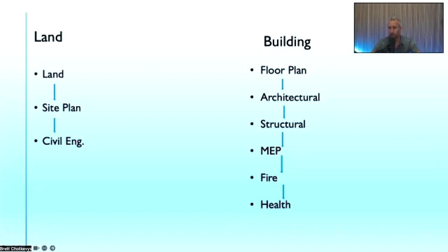So you lay out the 2D, then he's going to go through and build out, okay, now here's the walls, here's the roof pitch, where's the windows, what are the window sizes? I'll show you actually an example to put it in perspective for you, all the different things he'll have to do, including all the different ADA stuff, and then all the different local AHJ stuff for any authority, specifically like for licensure, having to put all of that kind of stuff in there. So once my architectural was done, my full plan set of architectural drawings, then I wasn't done yet.